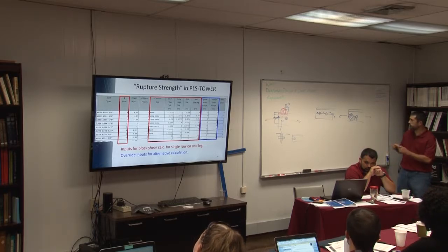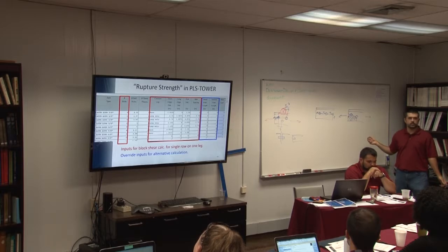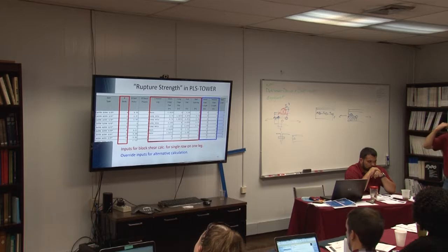Essentially it's all about our edge distances and our spacings. I can't give you a rule of thumb to say which one is always going to control over another one. I can just say that we're checking all of them and we're going to find which one is the minimum.